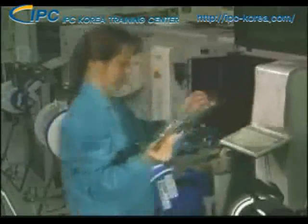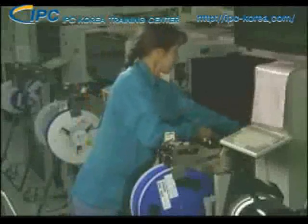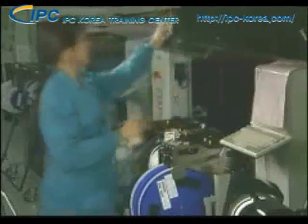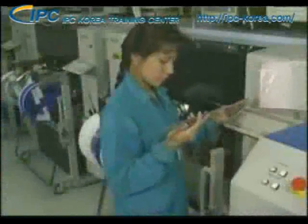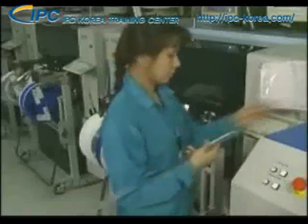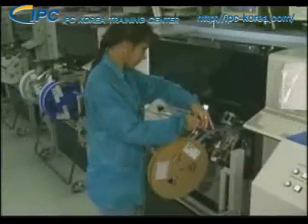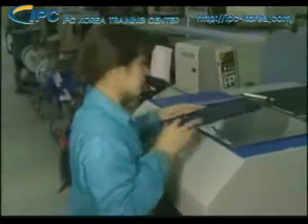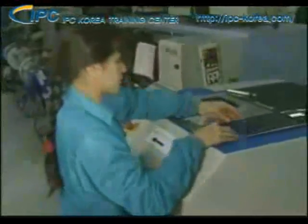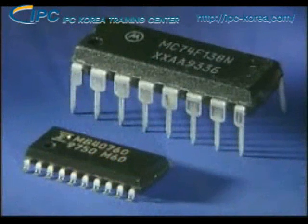Notice how the operator checks the part number on the reel against the bill of materials. That's because these components are too small to have part numbers marked on them. In addition, polarity or pin 1 orientation should be verified before loading tubes into feeders. It's also important to check pin 1 orientation when loading trays. Another difference is that surface mount components don't have long leads.